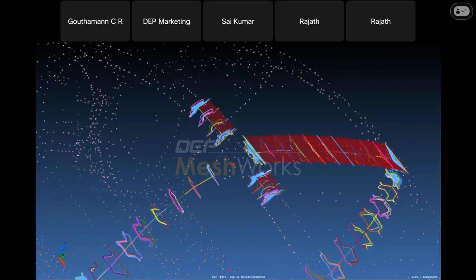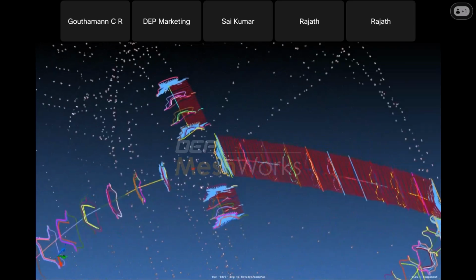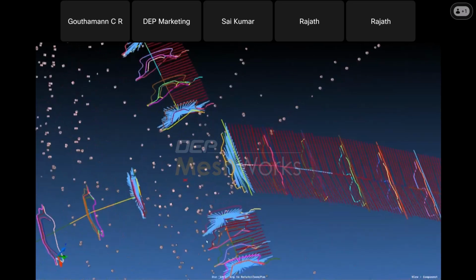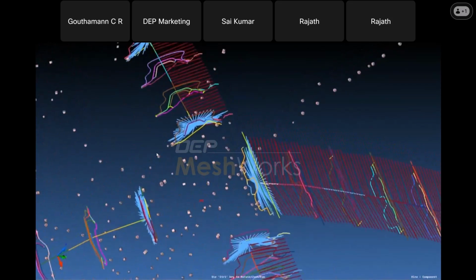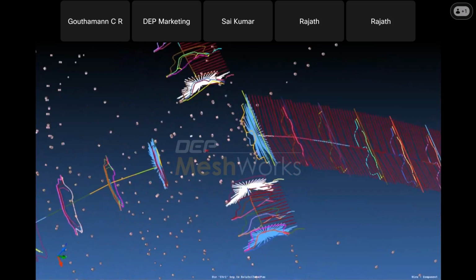So next I'll go with the beam joint modeling and select 2 opposing rigids as set 1 and these 2 opposing rigids as set 2. This is set 1 and this is set 2. And then select the center node.